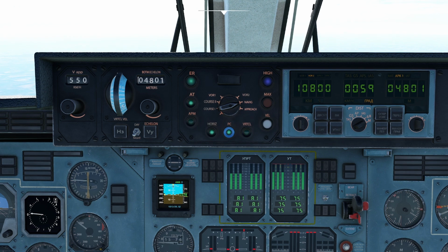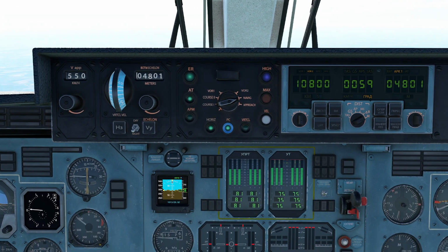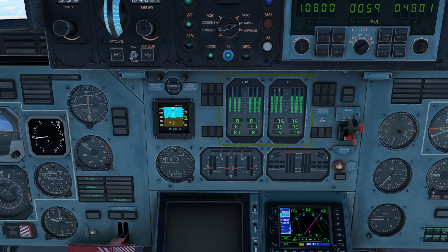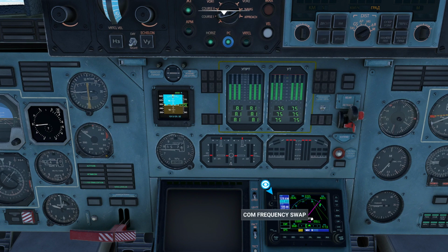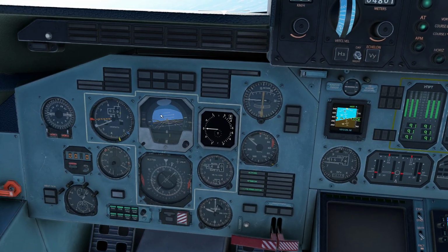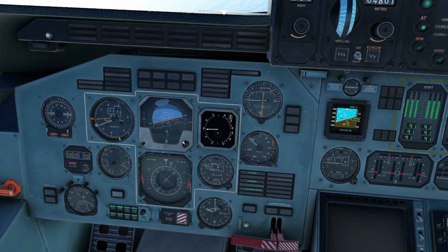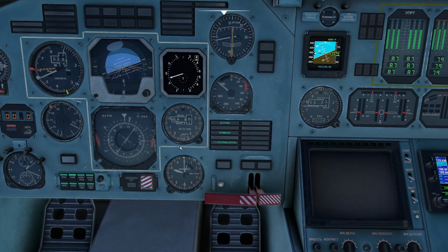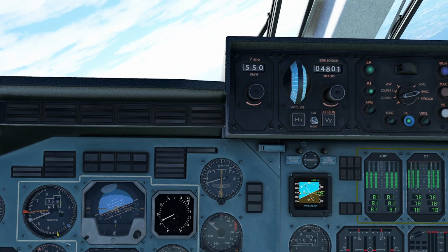course mode will automatically grab onto the desired course we want to be on as soon as we get ourselves to that course. If you take a look right now, we are just about to hop onto that course there, and what it's going to do is you can already see the aircraft start to take a right turn here as it starts to grab onto it. We know everything's working because we have course stabilization enabled.